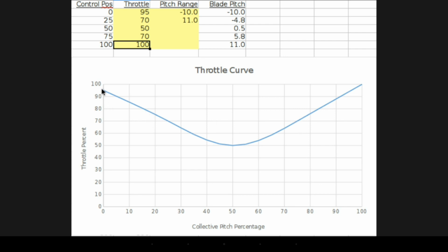So the spline smoothing with the 5 points, just like the spline waypoints in mission planning for ArduPilot, make this type of throttle curve pretty much infinitely adjustable with those 5 points by moving them around. And I don't know if I mentioned it, but this spreadsheet that we developed to visualize the throttle curve, we might make this available as a tool.